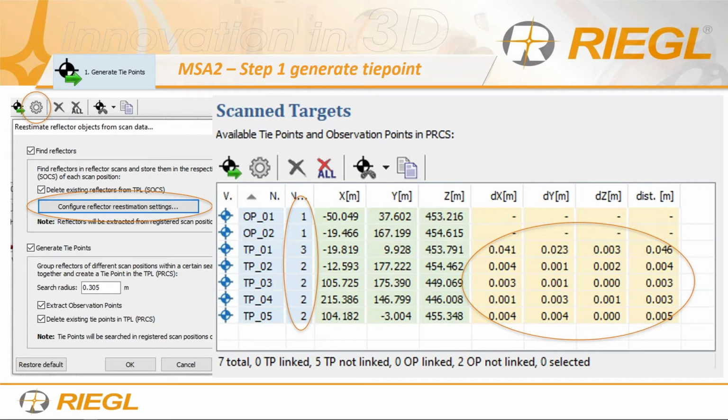Okay. You can even uncheck that. So if you have a good amount of survey control out there, you might just want to uncheck it and then move on to the find corresponding points. But this can also limit you from finding corresponding points as well.